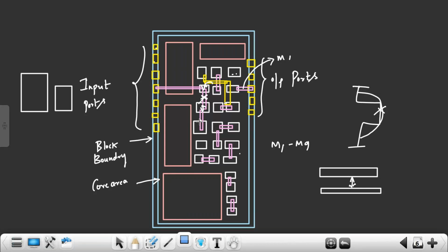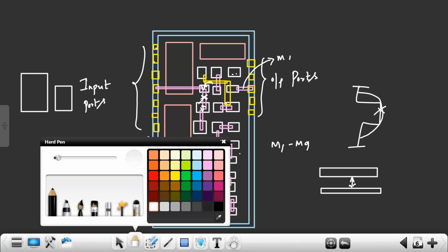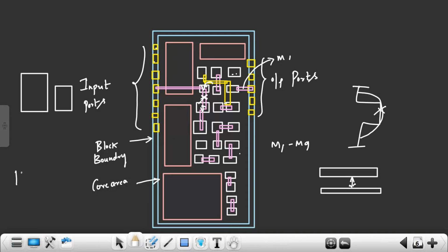In the higher perspective, you cannot understand this, but when you understand STA, you can understand how the speed and voltage are dependent. For example, for 14 nm, what is the voltage I can use? What is the VDD I can use for the cell? Based on that, the cell delay will depend. Based on that, the speed of operation will depend. It's not that if technology reduces, you cannot operate with higher speed, or that higher technology can operate. It depends upon the voltage. What is the cell voltage?